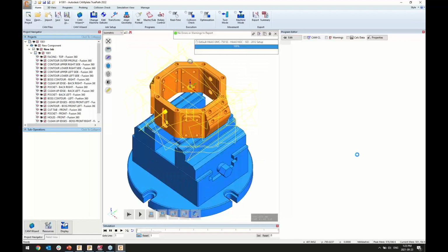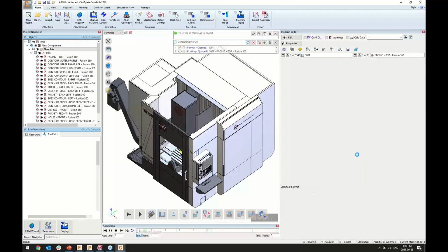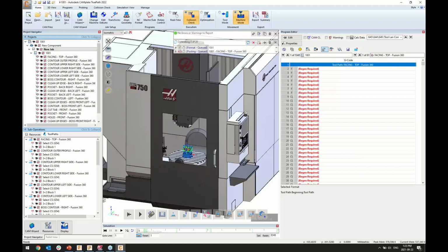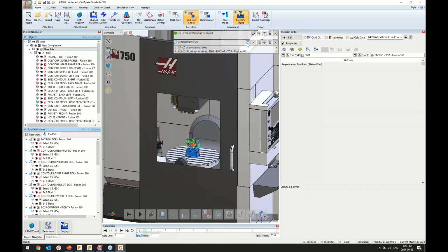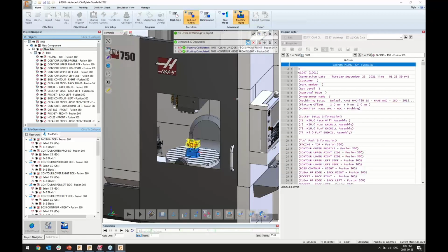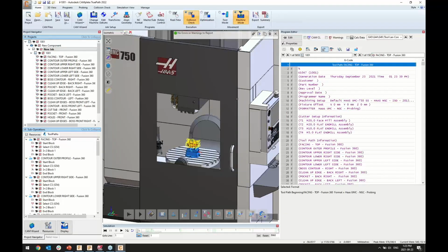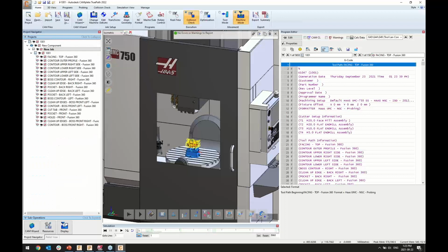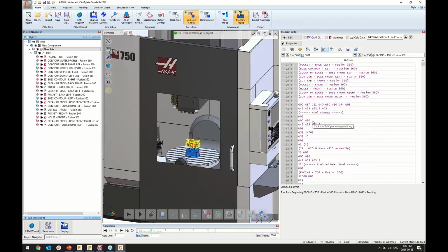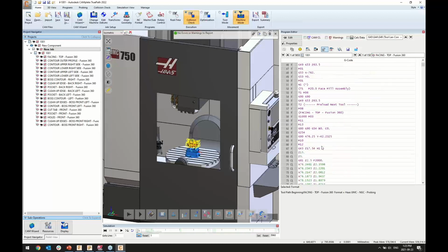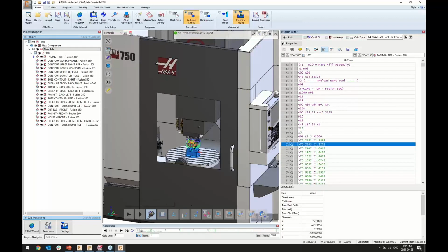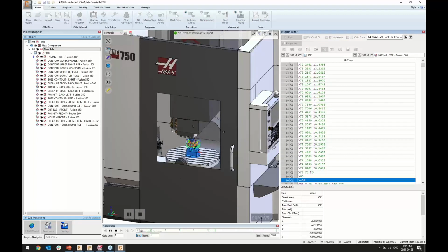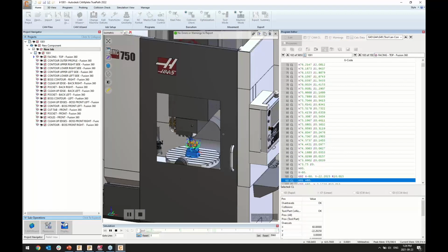So that means obviously the toolpath, the fixture, the part model, the stock, where all those elements are located in the machine environment. And at that point, this is really when we can start doing the actual code generation. So the software will check in the background what type of information has been used, how it is handled, and will start introducing some errors so we can see how the software will react to it. But really at this point, this is now the stage where we do have the G code that has been created, and now we can really start verifying exactly what the resulting motion in the machine tool will be from the toolpath that has been created.